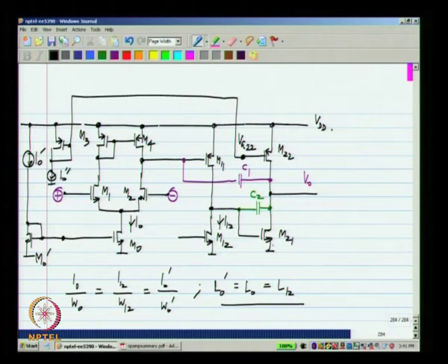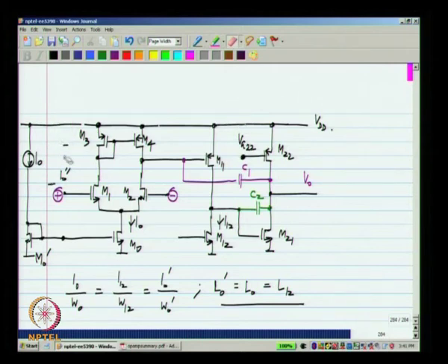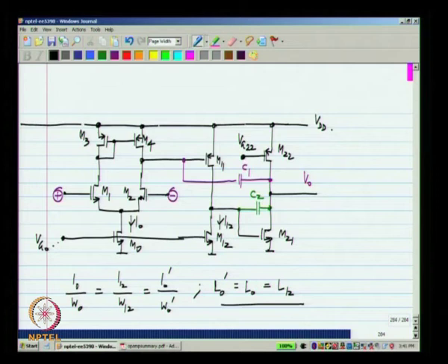So, that is how we bias the op amp, but it is very cumbersome if we show every transistor in the circuit. So, it is very frequently not shown, these current mirror devices are not shown and we show only that much. Okay. Now, the other thing is we have a current source going into the drain of the transistor and there is no other path for the direct current, the DC. Okay. Similarly, M22 is a current source that is feeding into the drain of M21.